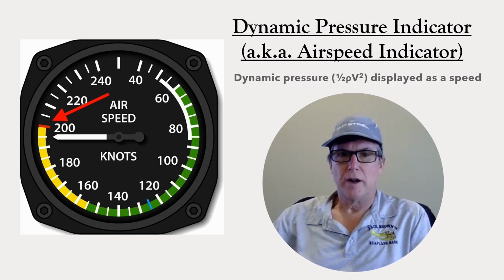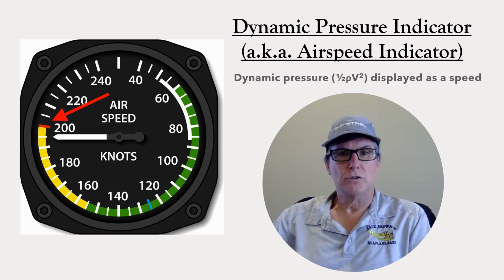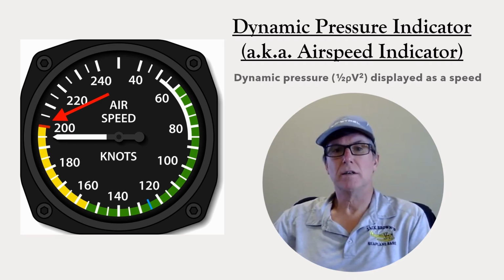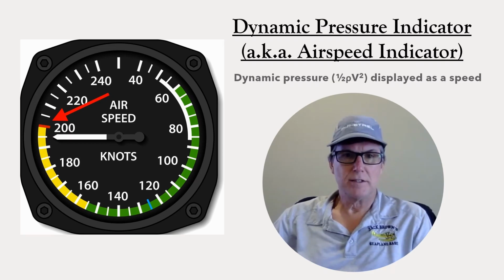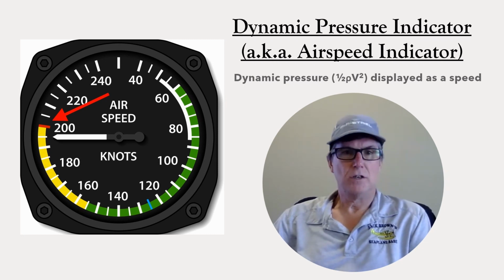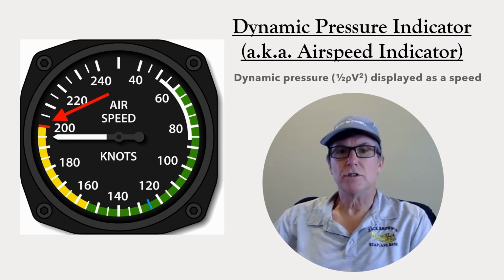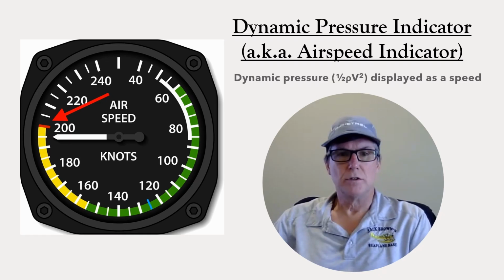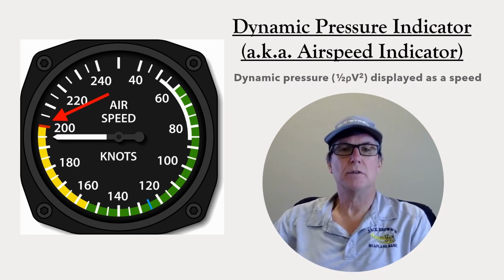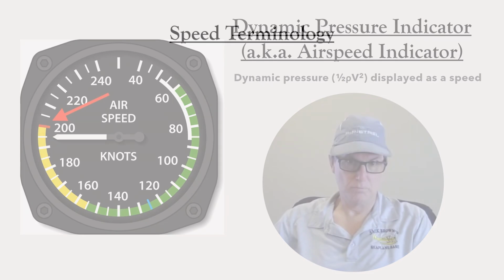In some aircraft, VNE is a true airspeed. If you're at a high density altitude, then the true airspeed will be higher than the indicated airspeed. If that's the case for your aircraft, then you'll need to consult a conversion table for your altitude to know what indicated airspeed corresponds to the present never exceed speed.